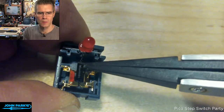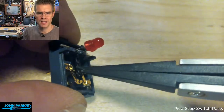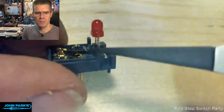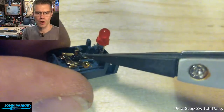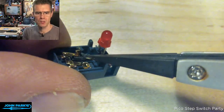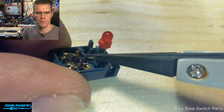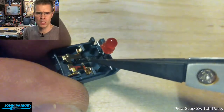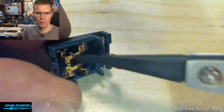That's what's actually contacting the top of this black spring here, and then it essentially buckles or draws. See, it bends, bends, bends, and then straightens down at the bottom. And that's what's flipping this metal leaf here between the normally closed and the normally open side.